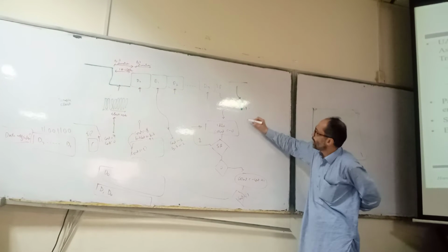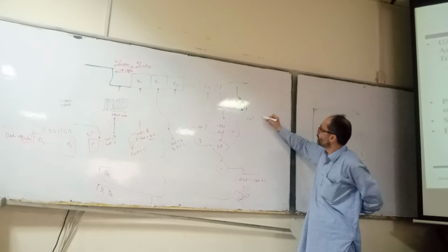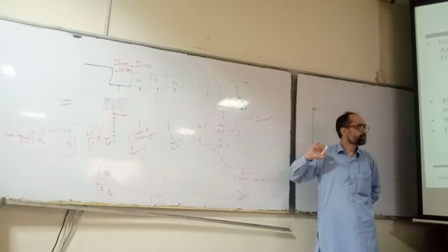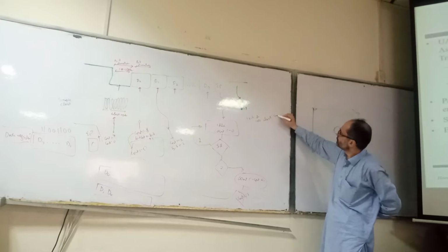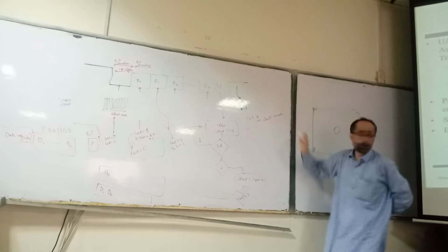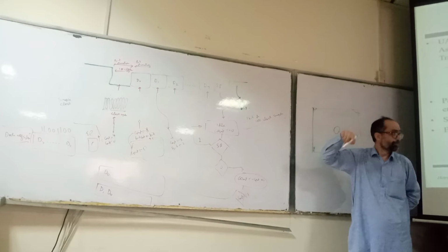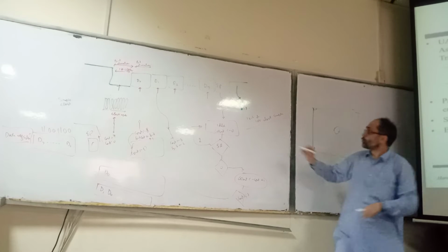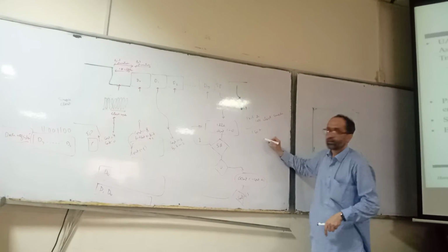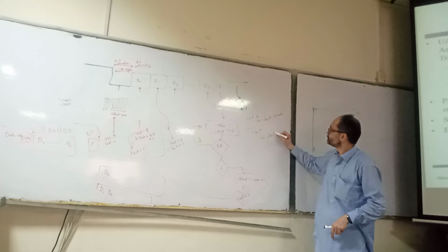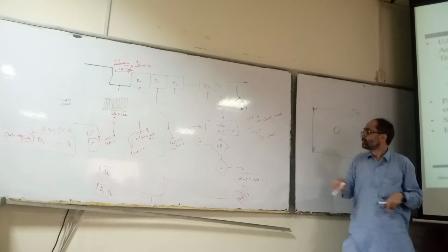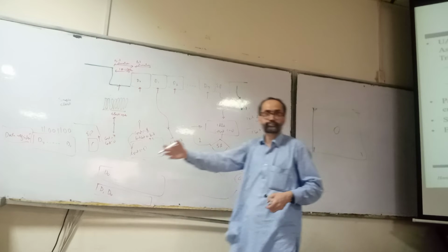Now let's assume that in the 1 bit duration, there are 100 clock cycles of the sample clock. If you double the baud rate, the bit duration is now reduced to half. So within the same 1 bit duration, it will be 50 clock cycles. And if you further double the baud rate, then 25, and so forth.